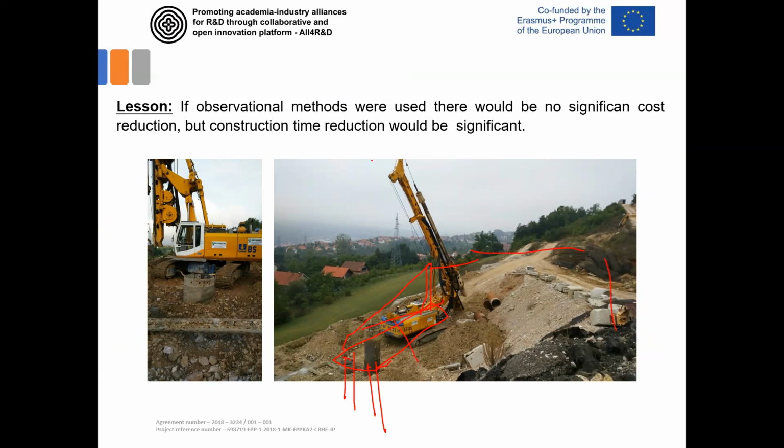So what could be the lesson? The lesson is that there would not be significant cost reduction even if we went for an observational method, since no doubt in these conditions this deep foundation had to be done. But maybe some construction time reduction could be significant and could be an option